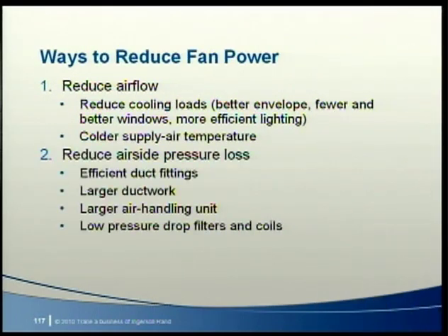The second strategy is to reduce airside pressure losses. This might include using efficient, low-loss duct fittings or slightly larger ducts, maybe even selecting a larger air handling unit. A smaller unit might have a lower first cost, but it uses more fan power, while a larger unit costs more initially, but uses less fan power. Then also look into low pressure drop filter and coil options.